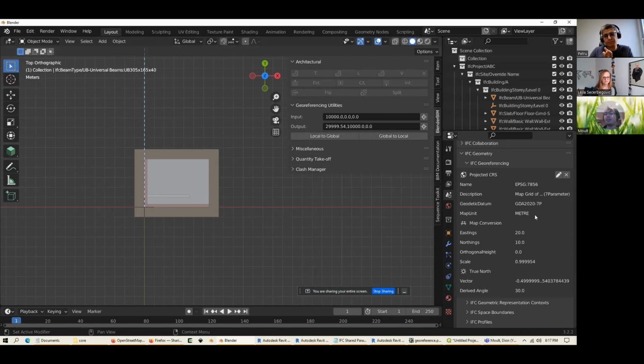And if you're not a surveyor, hold the surveyor accountable. Ring them up, ask them for these values. One thing they might actually tell you is, hey, we just approximated the scale to 1. So be it. Let them put it down in writing, enter it in as 1, and you have it on the project record. Everybody knows you're faking it slightly and it gets absorbed in the project tolerance if it's a small project, but at least you've done your due diligence in getting georeferencing absolutely correct.